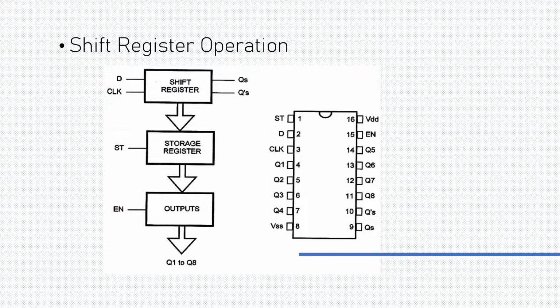For the data to be entered or shifted within the register, it requires the clock acknowledging the data pin. Upon acquiring 8 bits within the register, that value is ready to be moved out of the register for storage. That is when the storage pin is acknowledged and the data is shifted out of the register into the storage register compartment.